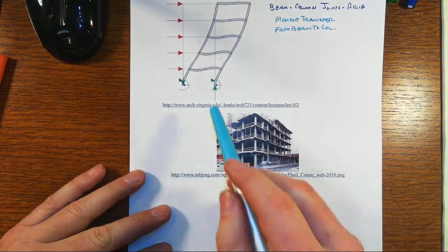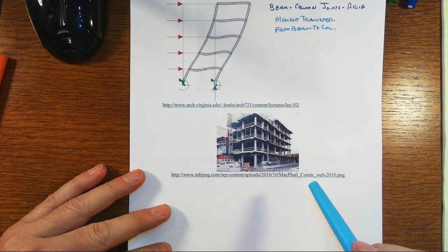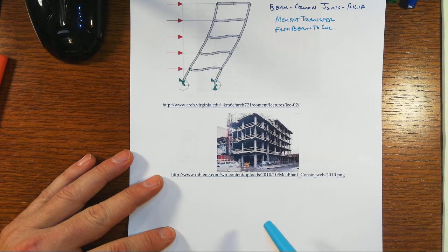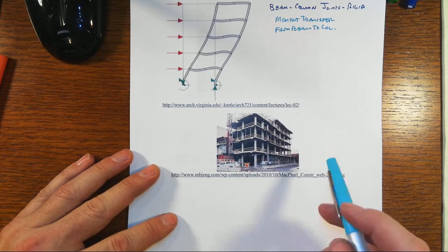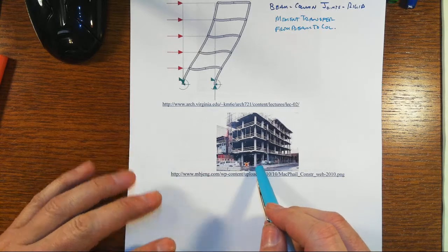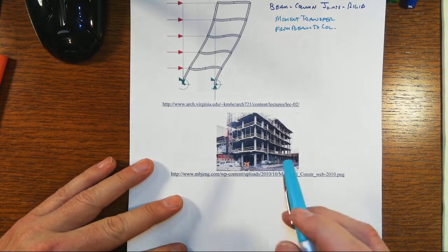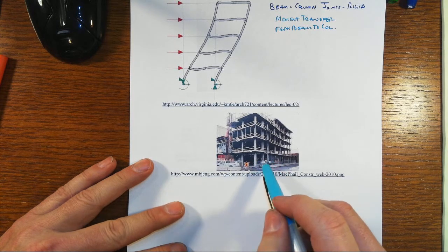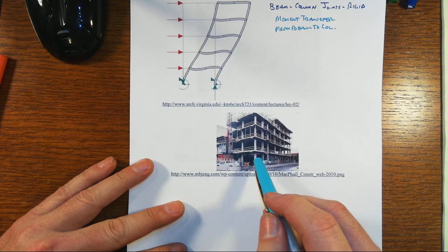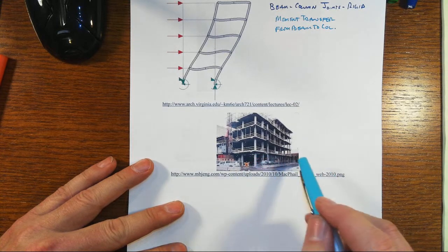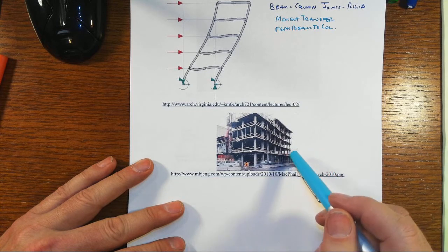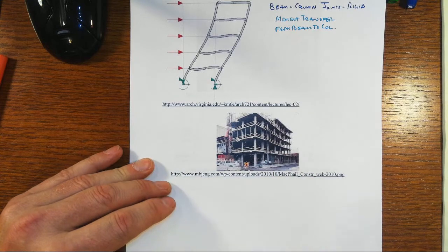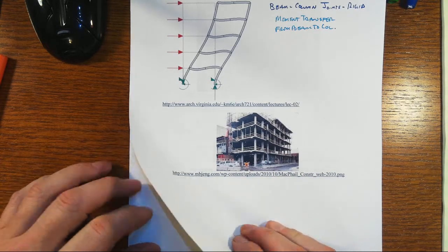Now in your structural system, you might or might not have a lot of these moment frames. In steel frame systems, these are strong enough, stiff enough that you may only have them in just a few locations throughout the structural framing system. Depends a little bit on the overall level of seismic hazard. But in cast-in-place reinforced concrete construction, the integral nature of how you make such a structure is going to mean that as long as you put sufficient detailing of the steel reinforcement through the beam column joint, you're going to have moment frames everywhere throughout that particular system, such as the kind of thing that you see here, which has also got some flat slab concrete construction in there as well.